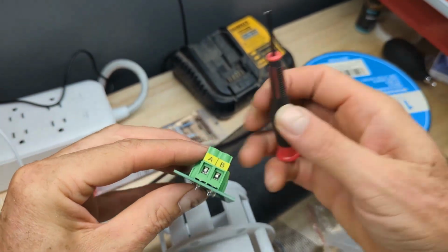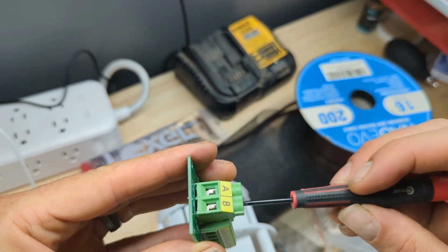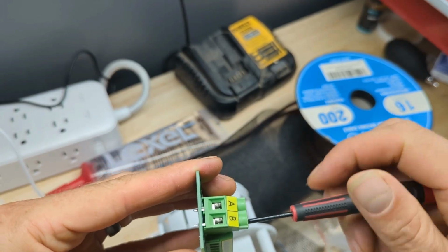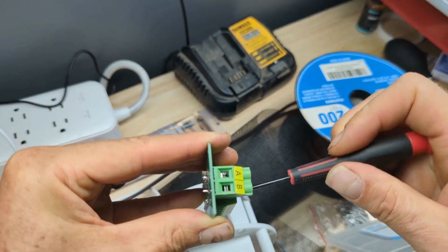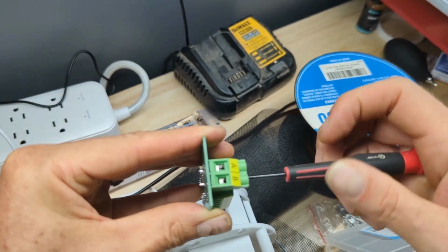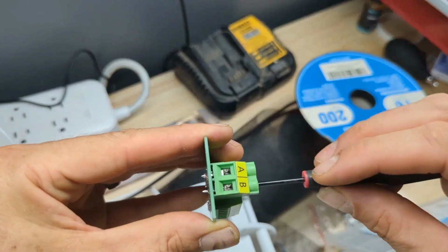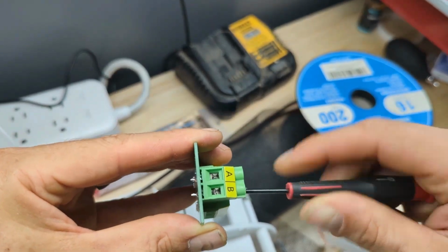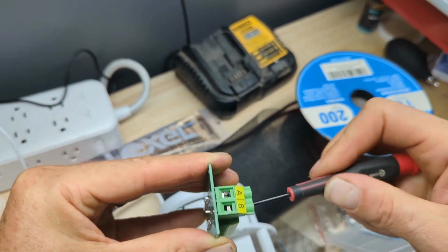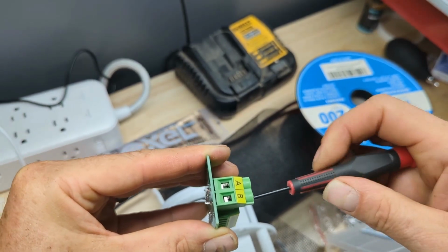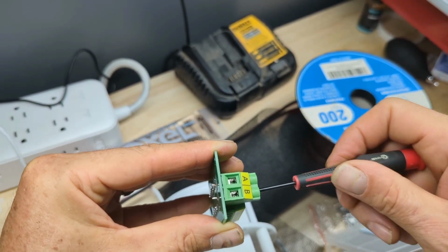Basically, when you thread these in and out, there is a little screw or a little cap that tightens in there. So as I thread these up, see how that tightens it up? See how that closes that gap on the B side? If your wire was in there, it would be getting squeezed and held tightly in that little bitty hole. Do that again just to make sure that the camera can actually see it. We'll tighten that up. That's tightening it clockwise, and then counterclockwise will open up the hole so you can put your wire into it and clamp it down.